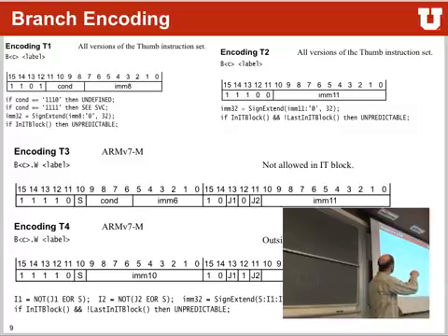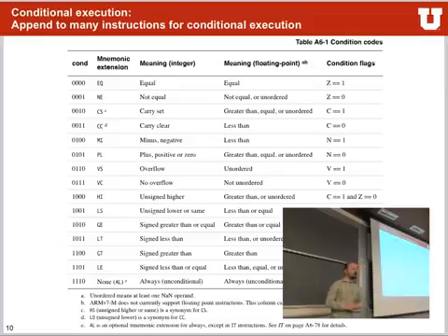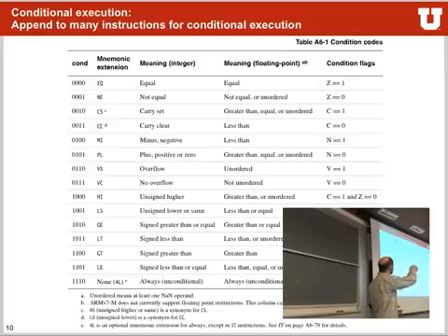So what are these conditions that we can have here? Well, we looked at them last time. There are a whole bunch of different conditions that act upon what's written in the status register itself. And I highly suggest you, if you look at your quick graph data sheet, you have all the encodings or all these little mnemonics in there, but what you don't have is this column here, which is actually telling you what it will do. I suggest you write this column in there by hand because sometimes when you're in the homework or especially in the midterm, you want to know, okay, what was this encoding again? And if you have it written there, it helps you a lot, trust me. So with these different little mnemonics, you can make functions executable conditionally. So you can execute a function depending on what the status register does.